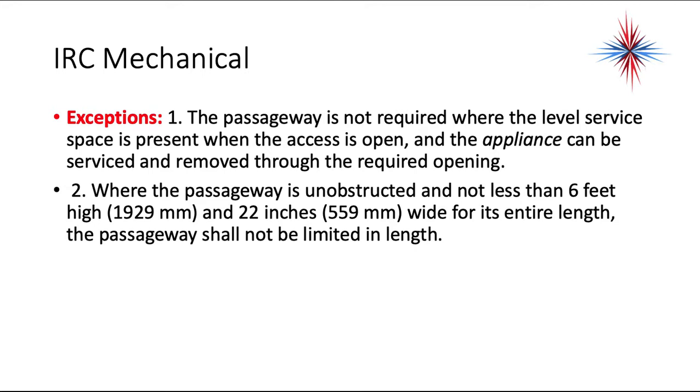Okay, the passageway should not be limited in length. In other words, if I go into a crawl space and I can stand in it with 6 feet high and 22 inches wide and it's not obstructed, I do not have to have a solid floor to walk on.